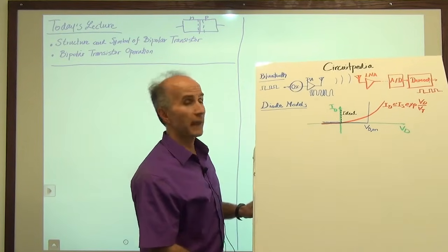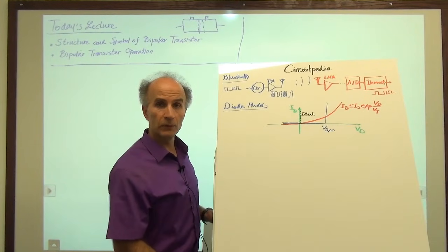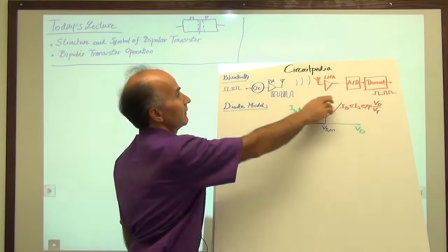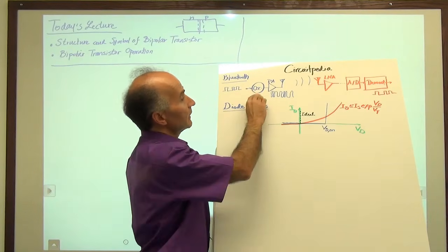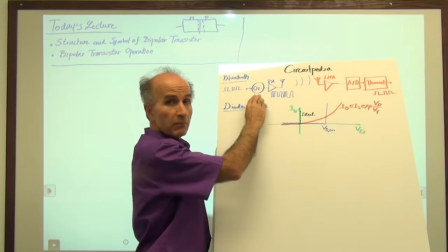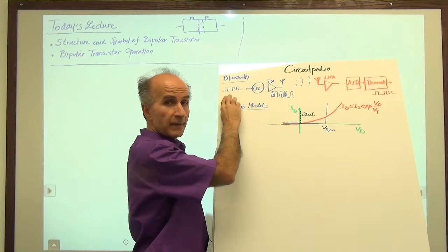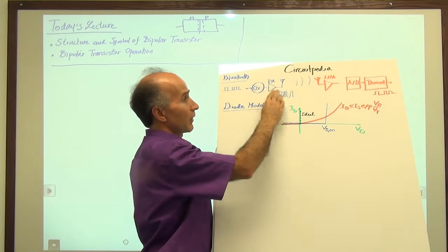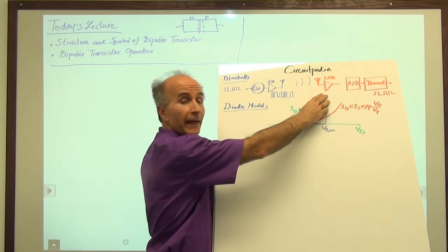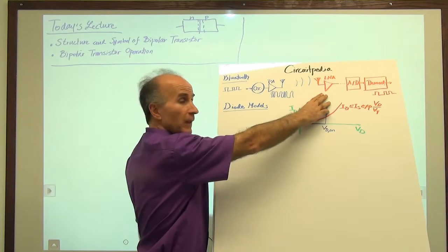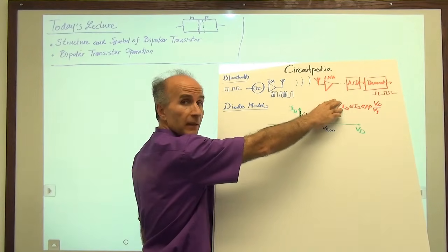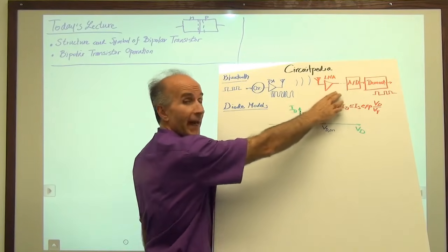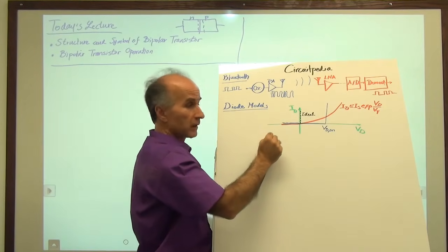So again, remember that when we designed the Bluetooth transmitter and receiver, we had an oscillator whose frequency was modulated by the ones and zeros, and then we had a power amplifier, and then on the receive side we had a low noise amplifier followed by some other processing, followed by an analog to digital converter, and then some more processing.